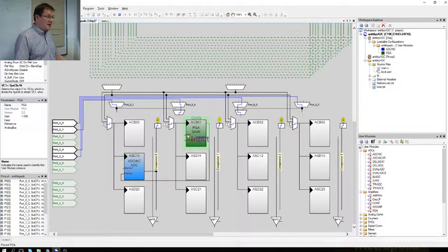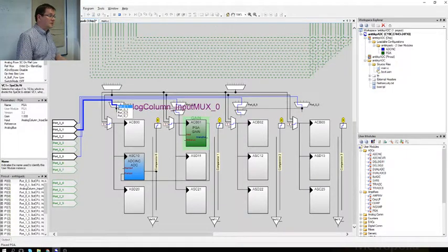Okay. And now I can actually connect the input to this 8-bit multiplexer, which basically can be used to connect to any of the port 0 pins. For example, port 0.2, that will be there. Or select from this multiplexer to get it from port 0.3. Okay, that's how it works. Quite simple to configure.